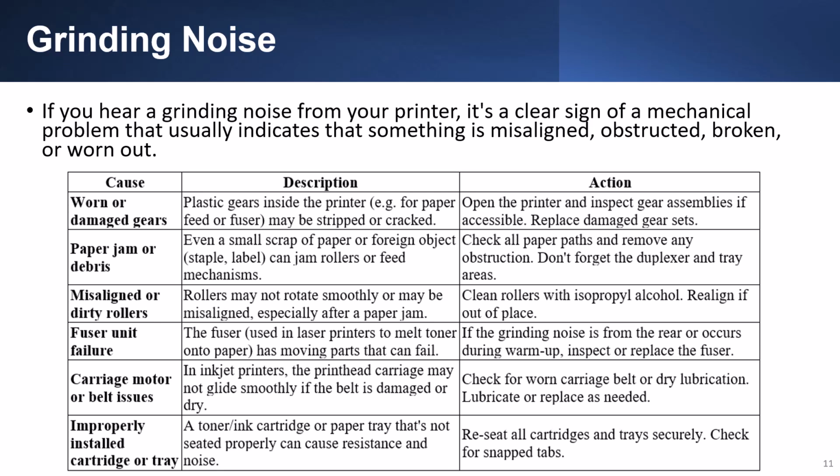Hearing a grinding noise from your printer? That's a red flag for mechanical trouble. Usually means that something is misaligned, obstructed, broken, or just worn out. Here's what to check. Worn or damaged gears. Open the printer and inspect the gear assemblies. Replace any gears that show signs of wear or damage.